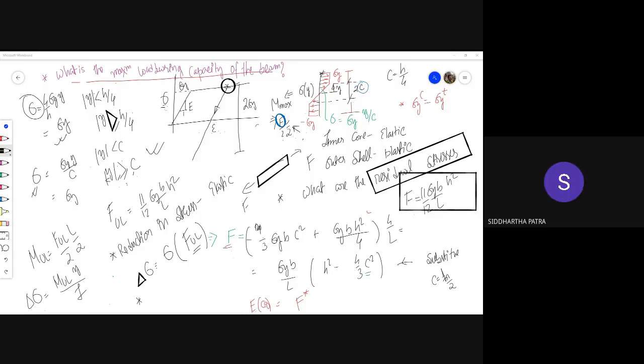We are doing unloading here, so the unloading process is elastic. Okay, and actually the span of elastic unloading extends in the compressive side as well. So the limit on unloading is twice sigma y, whereas when you were loading from the origin, by the time you reach sigma y, you started having plastic deformation. So the entire unloading process is going to be elastic, no doubt in that.